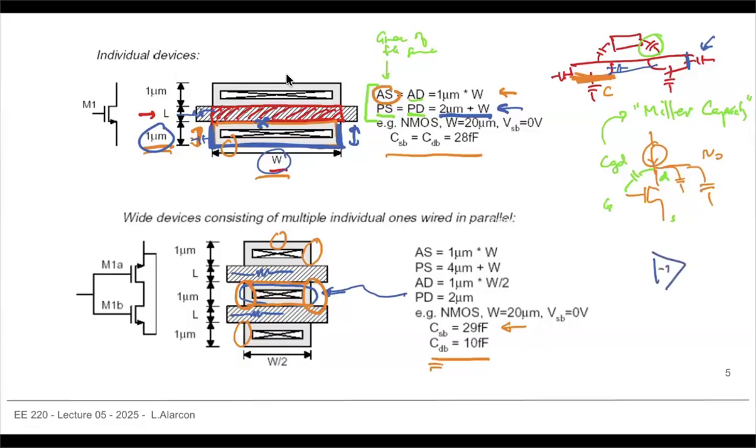That's because, if you remember, if I have an inverting amplifier, something like minus A, what happens if I actually put in a capacitor between the input and output of my amplifier? If I put in a capacitor between the input and output, the question is, how much current do I need to drive this particular amplifier?